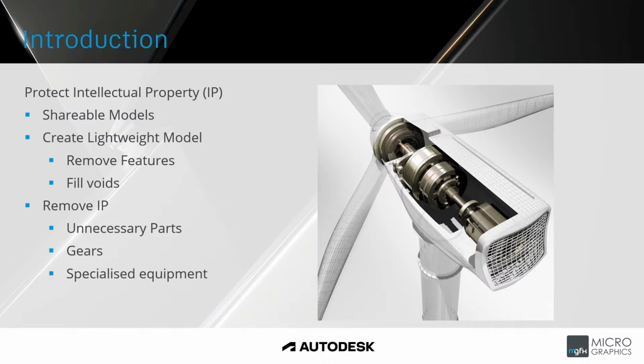But you don't want to give them the full model. You don't want to give away your IP. And they definitely don't want to have a fully detailed, heavy model where they are going to place, let's say, 100 of them in a field. And that would slow their design process down. So you want to create a lightweight model. And we're going to look at some of the tools that allow us to do this, where we can remove features.